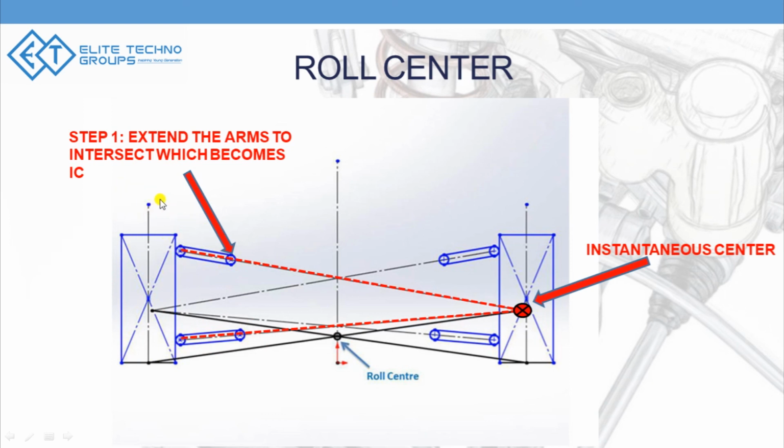So when it's inside the body packaging, it's very important to know the path your wheel follows at all bump and steer conditions, so that it can maintain the minimum clearances with all the surrounding parts around the wheel, because this is one of the critical safety aspects. You can't have your wheel interfering when you're driving at 100 kilometers per hour and suddenly turning, because of the wheel compression it moves up and interferes with one of the parts. That's one of the safety hazards.